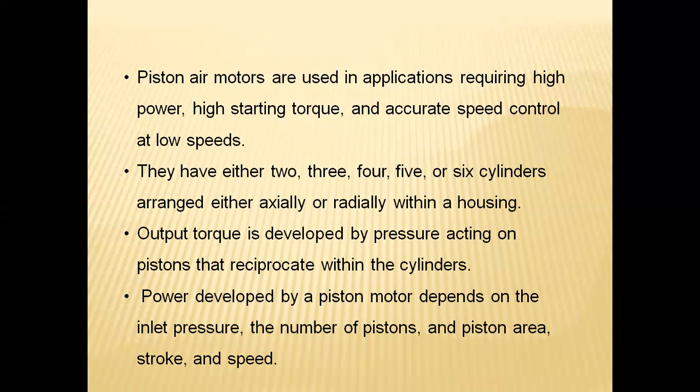Having two to six cylinders arranged axially and radially within a housing, output torque is developed by pressure acting on pistons that reciprocate within the cylinders. The power developed by a piston motor depends upon the inlet pressure, the number of pistons, the piston area, stroke, and speed.